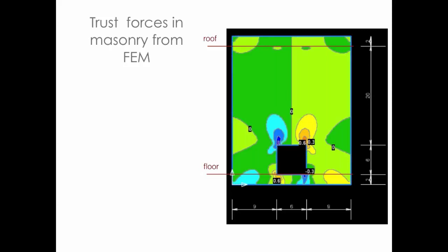Thrust forces, what do those look like? Those actually aren't that 1-to-1 ratio. That was an empirical method. That's something that you can very quickly do, a quick empirical check to see if I have enough thrust capabilities. This wall scenario, I'm probably not too worried about. I have a long length of the wall outside of the opening to resist whatever the thrust loads are. But they're actually pretty small, right? I have so much height above the opening. You can see within the stress contours, you can see arch upon arch upon arch all the way up the height of the wall. It very easily distributes the force.